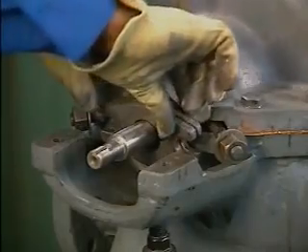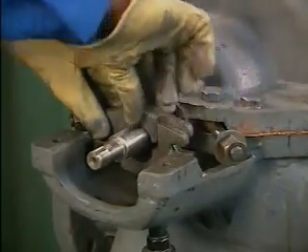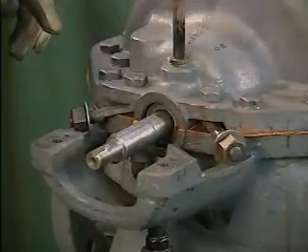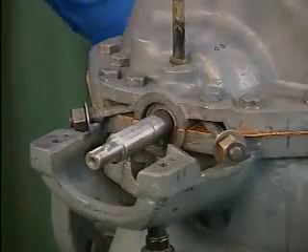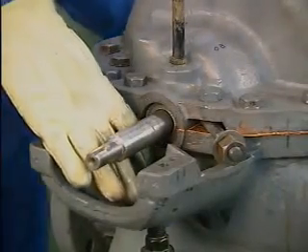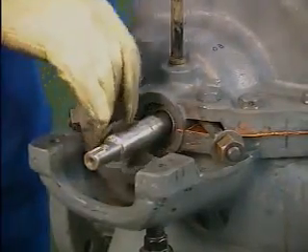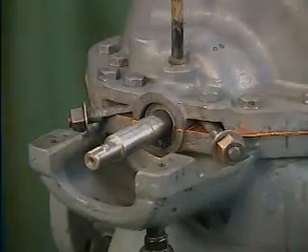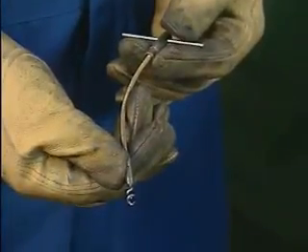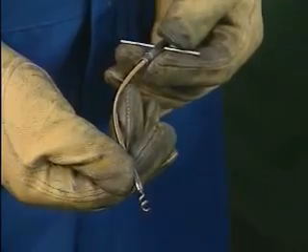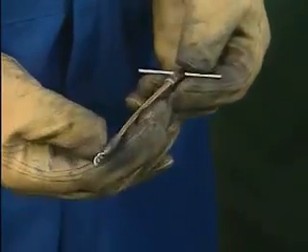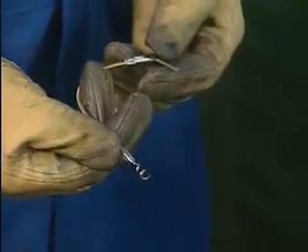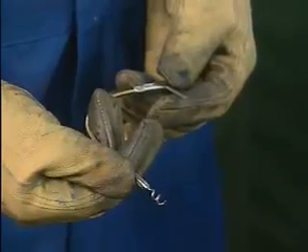This pump has a two-piece gland follower that allows it to be removed from the shaft. If an application has a single-piece gland follower that cannot be completely removed, the gland follower should be tied out of the way along the shaft. To remove the old packing, the mechanic uses a tool specially designed for this task called a packing puller. It consists of a corkscrew tip, a flexible shaft, and a handle.